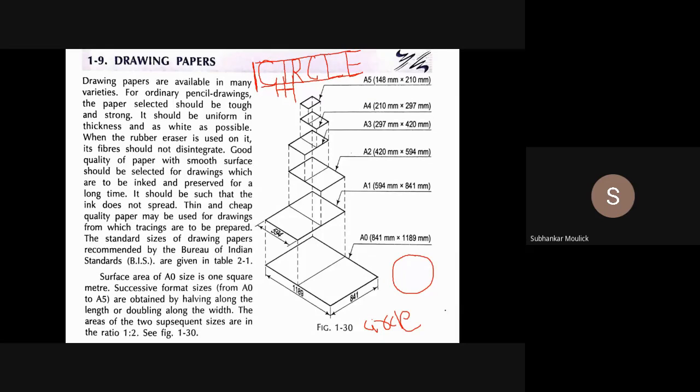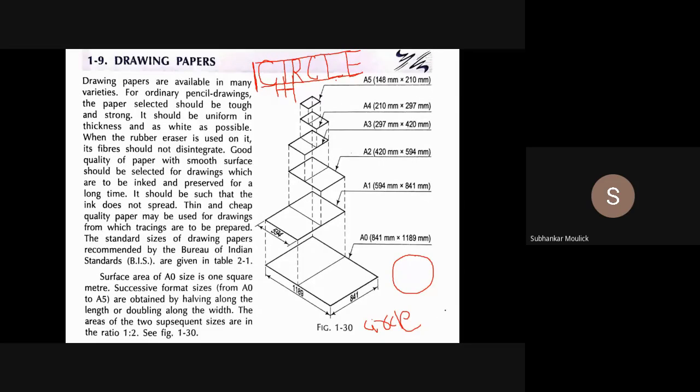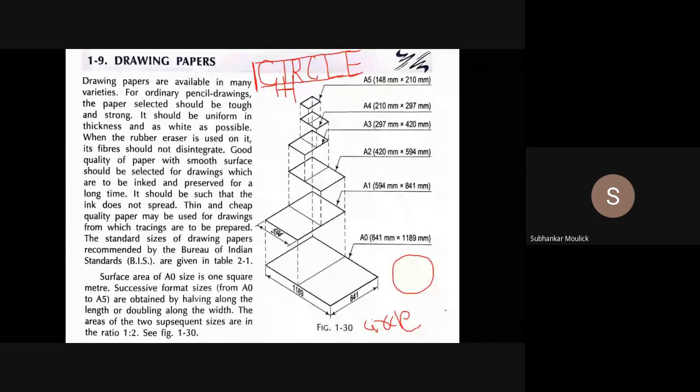See, these two horizontal lines you have to draw with either H pencil or 2H pencil. Why? Because it should not be highlighted. Only your heading will be highlighted. So the heading will be drawn with HB pencil, and these two horizontal lines, which are a supporting drawing in order to write the heading, you have to draw with H pencil.